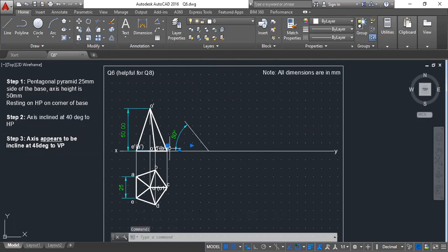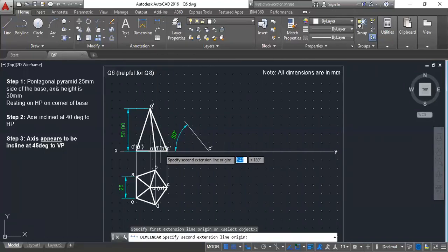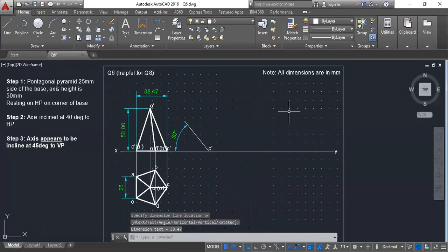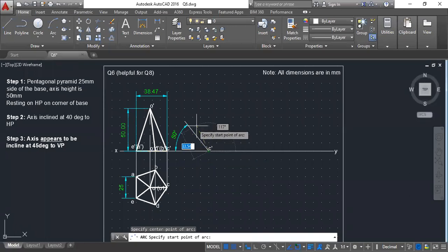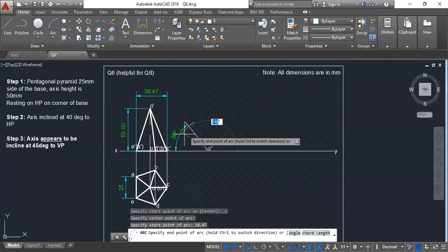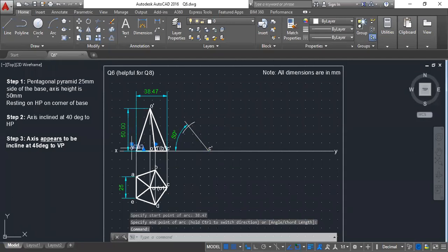Once that is there, to the rightmost point, whatever we have, place it there first. So this will be the rightmost point. After this, take your compass and measure the distance between C and E. You don't have to write this, I'm just showing you. Using your compass, measure this value, and using the same length with C as the center, draw an arc to get the point there. Then you get the point here, that is E prime, A prime.